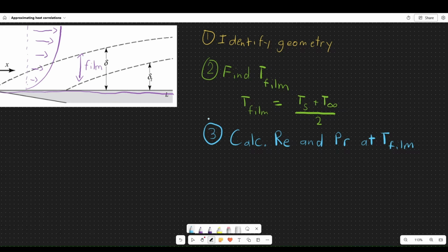So Reynolds number, right? Some of you might know the Reynolds number is basically a dimensionless parameter that describes the flow of the fluid. So a high Reynolds number is usually a turbulent flow, versus a low Reynolds number is a laminar flow.